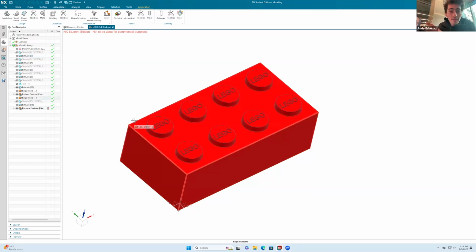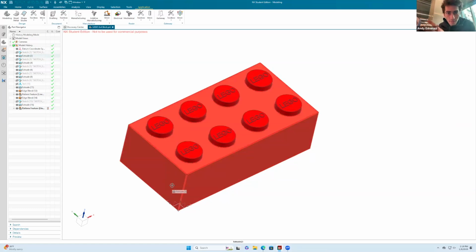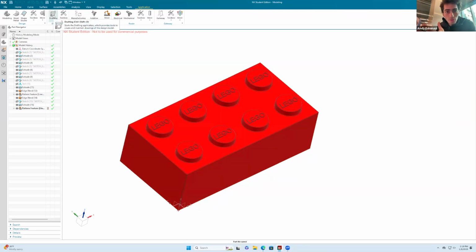What that means is that I save the part and it not only has the 3D model, you would be able to make the engineering drawing within it. I'm going to make an external drawing, so I'll go here to File and create a new drawing from scratch. I prefer that approach a little bit more because that creates an individual file for that drawing.